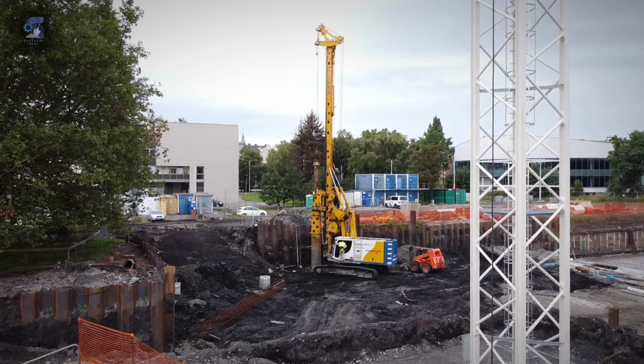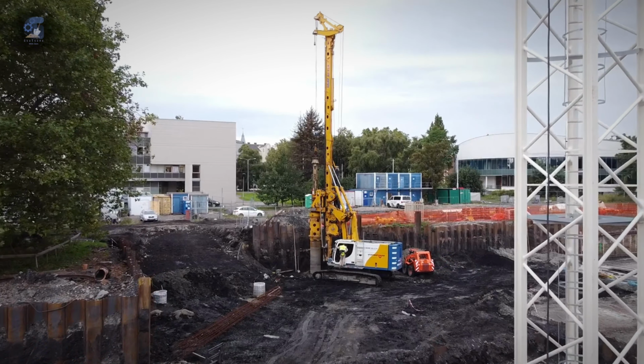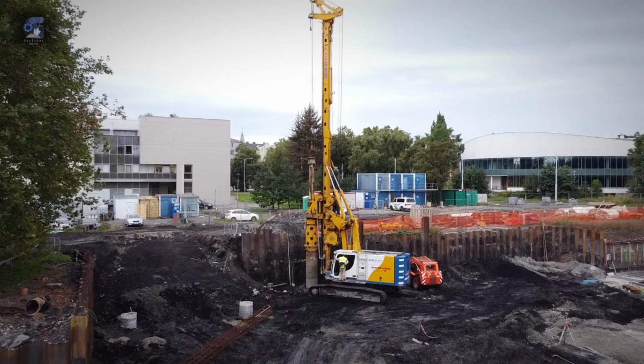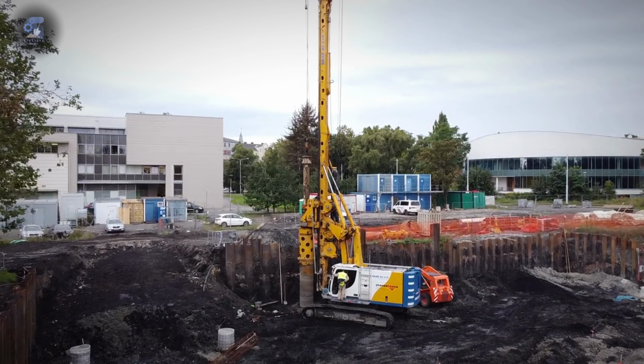They are best used in power foundation design, where they can predict the friction capacity and end-bearing capacity of piles more accurately than traditional empirical methods. They are also used in the foundation settlement area, where they can estimate the settlement of shallow and deep foundations in various soil types. They are also good at correlating soil and rock parameters such as relative density, shear strength, and unconfined compressive strength. As of late, artificial neural networks are being used to evaluate the potential for soil liquefaction during seismic events.